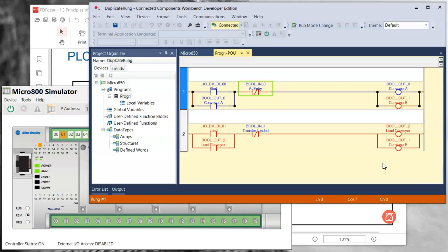And then, of course, being that we also have the left or right conveyor, depending on which direction we move the box in, we would probably have a fourth rung controlling those left and right conveyors as well. Okay, so hopefully this helps explain a little bit more. Next time in the lab, we'll come back into this and go back to the drawing board, so to speak, and see if you can redesign the program and get around this situation with the duplicate coils.